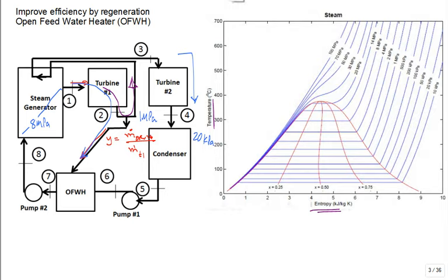If you grab off 8 MPa, here's the line of constant pressure of 8 MPa. Goes like that. And then if you also get a line of 1 MPa, here's the 1 megapascal pressure on a temperature entropy diagram. And then the line of about 20 kilopascal would be right here.